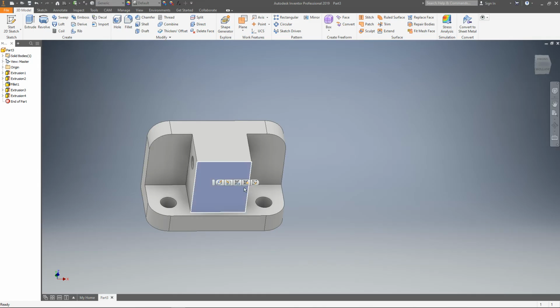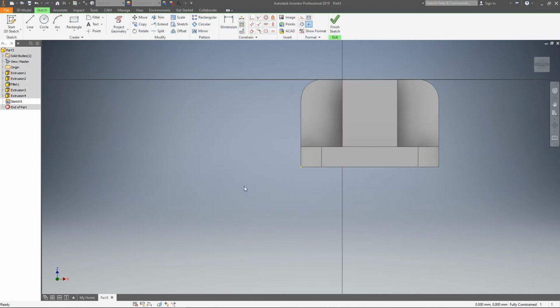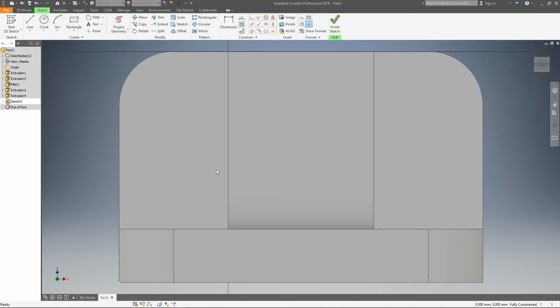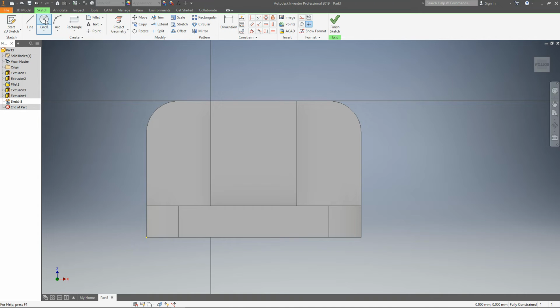So I'm going to start a sketch. Okay, I'm going to make a circle. Again, the radius is 12. That makes the diameter 24. Enter. Now I'm going to do a rectangle. We know that we need to cut some other stuff here. I'm going to start at the quadrant, and you can see it turns yellow when you get to the quadrant.